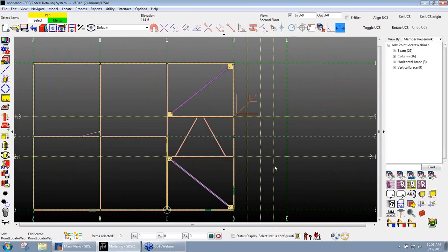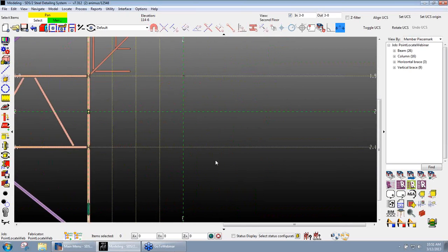So that was online. We showed you toggle annotations point, which turns my temporary points and my dimensions off. And then we also saw how we can type in either the angle, or the dimension or the distance that we want to pick our points as well. The next thing we'll look at is what we call polar point.